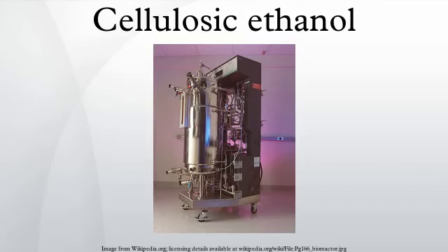Chemical pretreatment of the feedstock is required to prehydrolyze hemicellulose, so it can be more effectively converted into sugars. The dilute acid pretreatment is developed based on the early work on acid hydrolysis of wood at the USFS's Forest Products Laboratory. Recently, the Forest Products Laboratory together with the University of Wisconsin-Madison developed a sulfate pretreatment to overcome the recalcitrance of lignocellulose for robust enzymatic hydrolysis of wood cellulose.